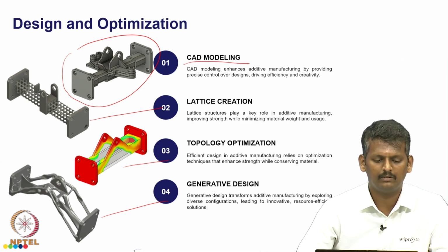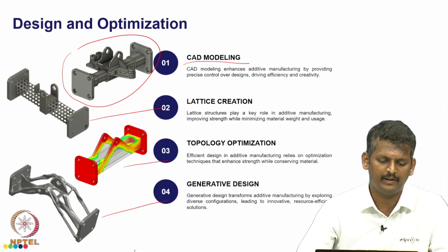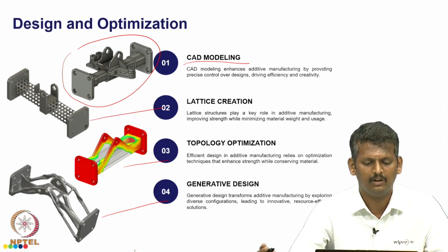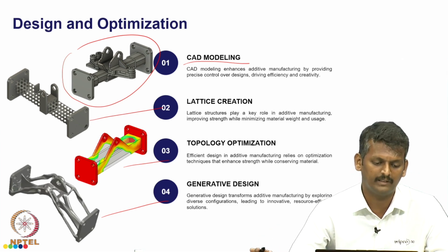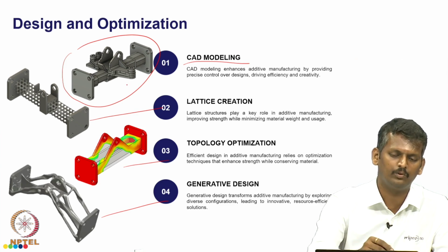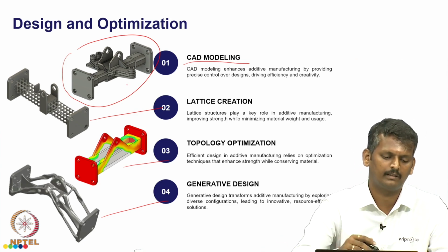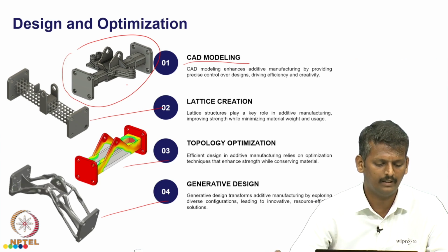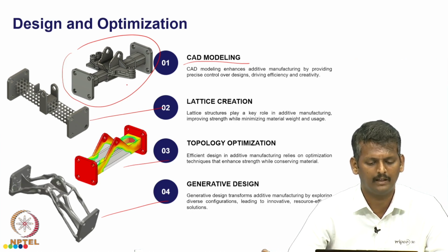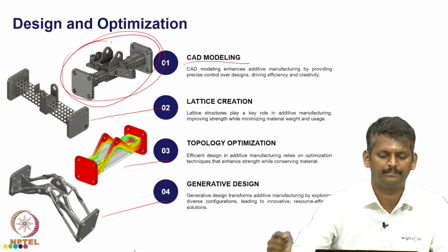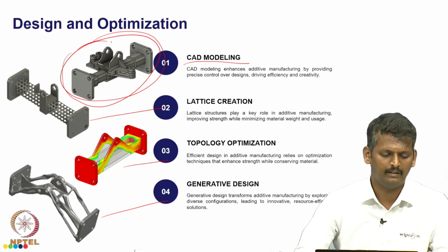That means it is not designed for additive manufacturing, it is designed for conventional manufacturing purposes. But when we implement it into additive manufacturing, all the design guidelines and methodologies can be implemented into this design and it can be part consolidated. Currently it is not a part consolidated design, whereas we can do the part consolidation on this kind of existing designs.